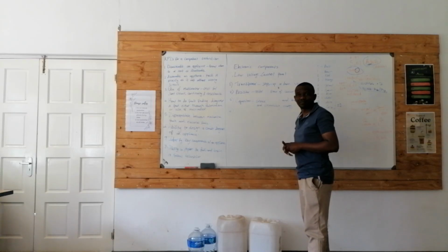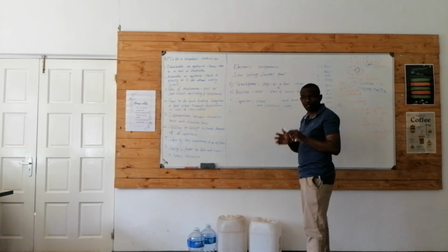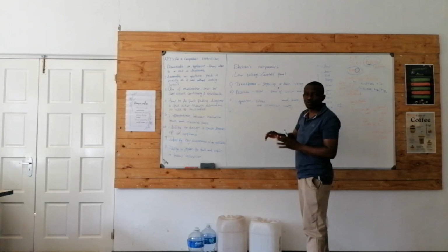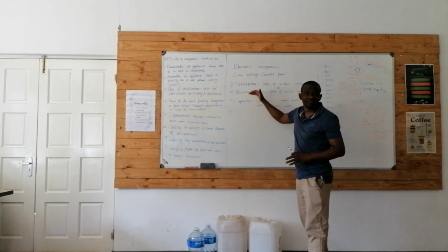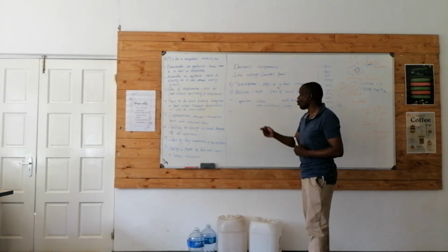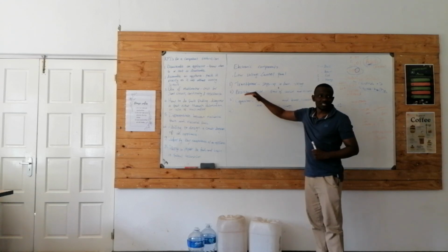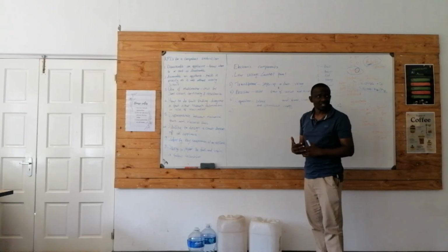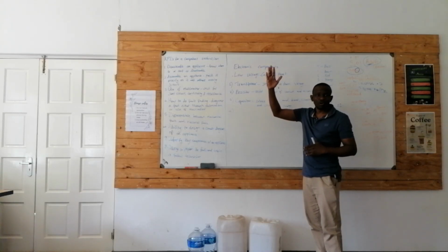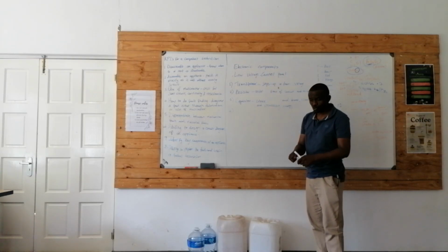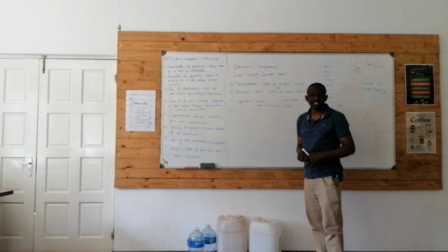What do we use on the resistor? We use ohms or continuity to test it. But in most cases, when we use continuity, we are unable to get anything from the resistor. So if you can't interpret the stripes of a resistor, use the high range of ohms on the multimeter, so that you don't make the mistake of using 200 ohms, finding nothing, and deciding the resistor is not working.